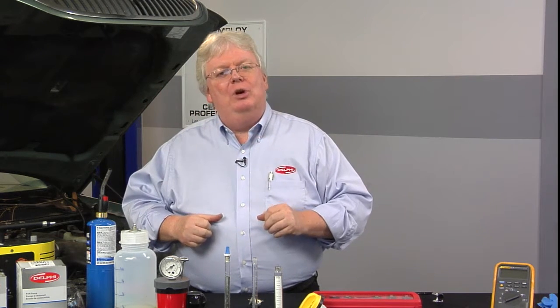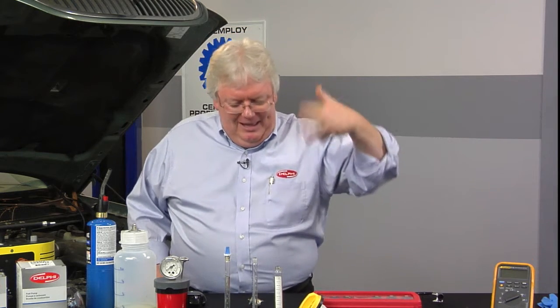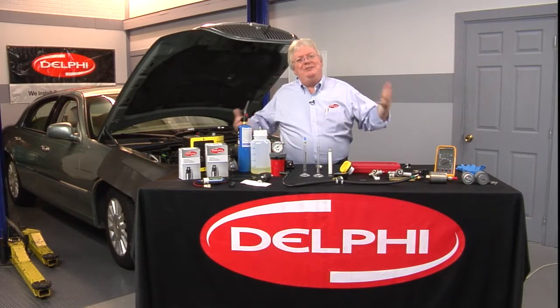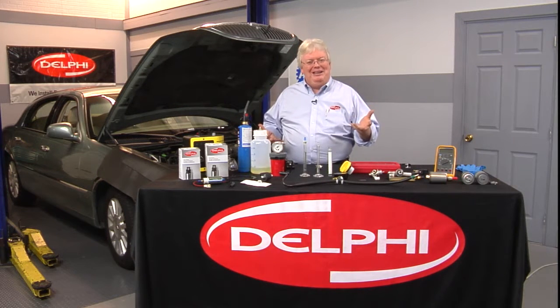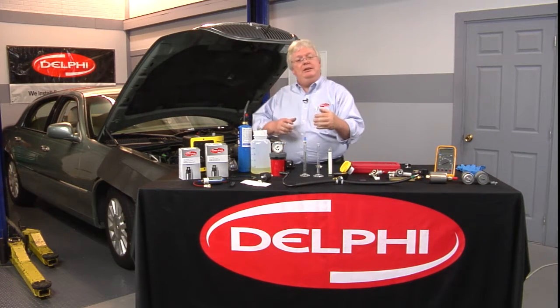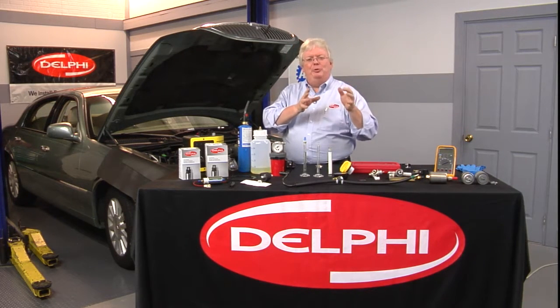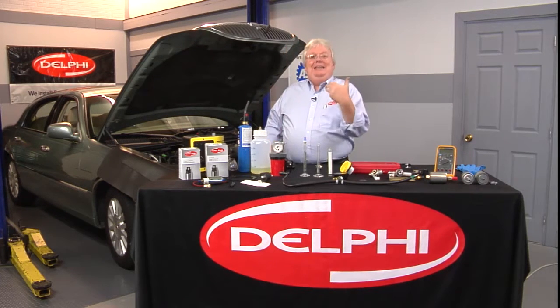Oftentimes you will have more PIDs on your factory level or OE level aftermarket tool than there are applicable to the vehicle. If you had the true factory tool, you would just have the PIDs that are germane. They're actually valid. I've actually seen on some aftermarket OE level tools a diesel injector PID or a glow plug PID for a gas engine. So you know something was really cooking with that, right? So those things happen, and my gut says that's probably what's going on, especially, Pete, if you've seen the same number for both short-term fuel trim bank 1 and short-term fuel trim bank 1 sensor 1. If they're the same number, it's the same PID.